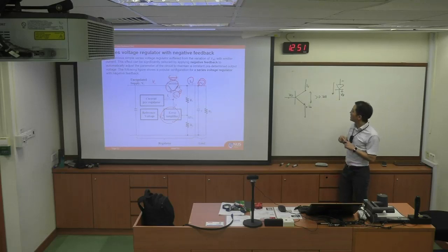But I said that's when the transistor gets into saturation. Even before you reach this value, if the collector voltage goes too low, then distortion heavily happens. So if I'm a good designer, I'll probably multiply this by 10 and give no less than a 2 volt difference between collector and emitter.